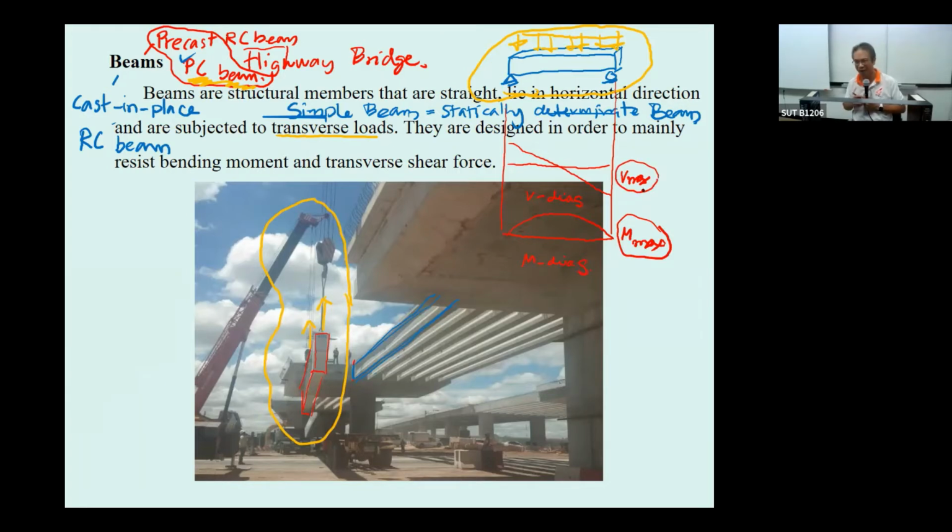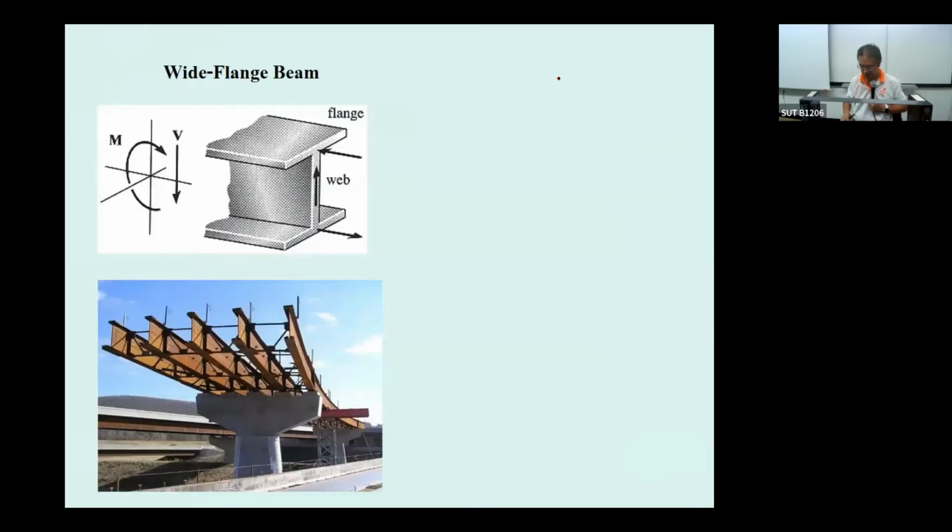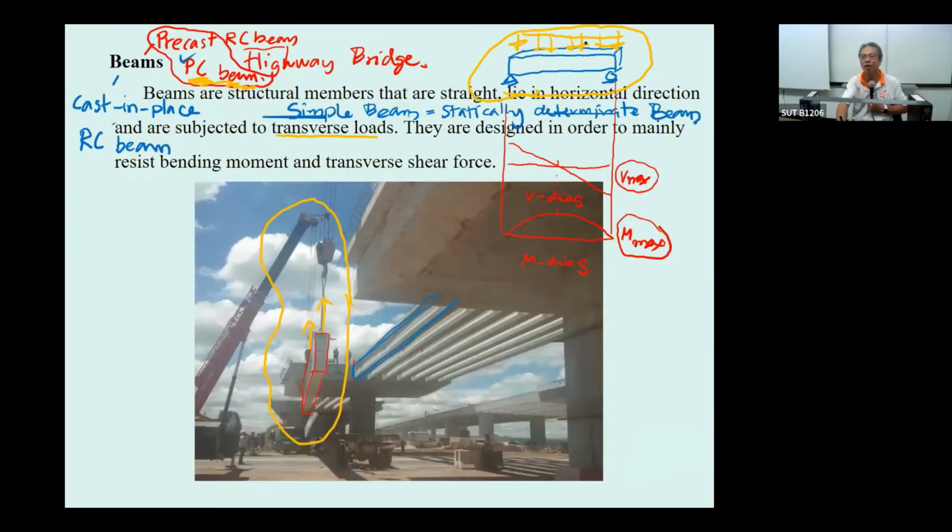If you can record it, it's going to help you, okay. And usually if this one is W and the length here is L, you will know that this is going to be WL over 2. This is minus WL over 2. The maximum moment here is going to be equal to WL square over 8. Okay, you can go back to what you have studied.